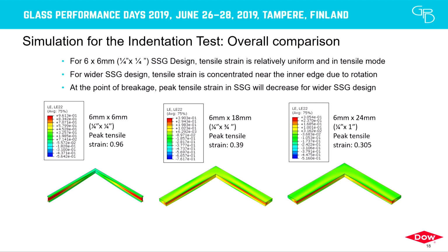Same, if I put the 3 deformation modes next to each other, you observe the difference in deformation that is influenced by the aspect ratio, and we can see that the tensile strain is really always concentrated near the inner edge due to the rotation.